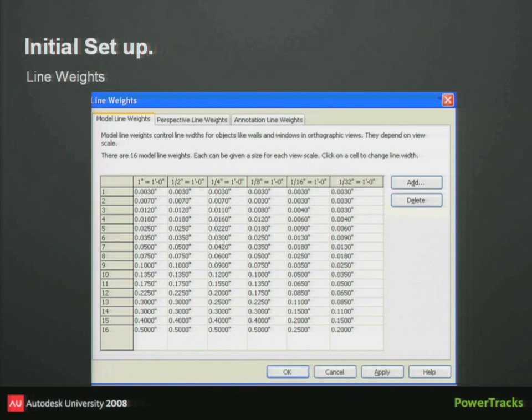And let's say you have all those set up for the units. In traditional CAD standard, you have all different types of thickness of line types. Let's say the supply ductwork is different from exhaust ductwork line thickness. For instance, let's say your double line supply ductwork line thickness is different than your single line ductwork thickness. So this is where you have to set up.